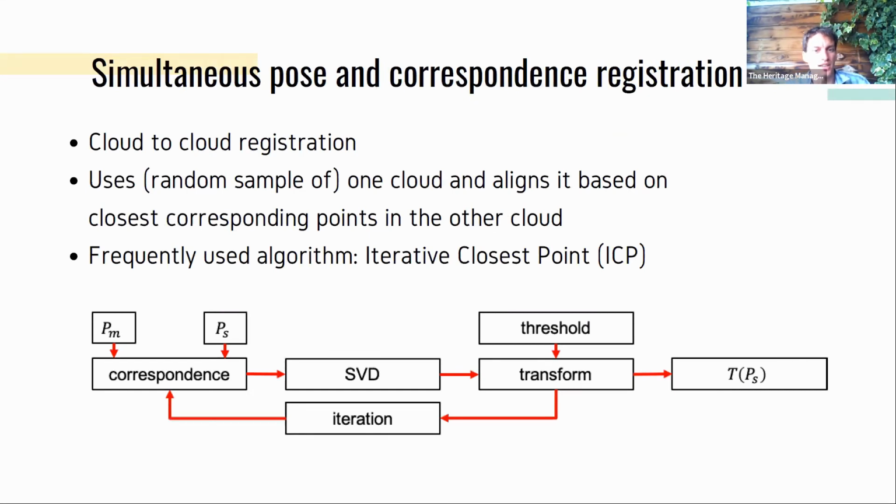A very interesting way of working with laser scanning without using these targets is the cloud-to-cloud registration, which is, a priori, less accurate than target-based, because we will not explicitly measure our targets or our reference with highest accuracy or highest resolution, but we will use the entire data sets for the registration, for the self-registration actually.